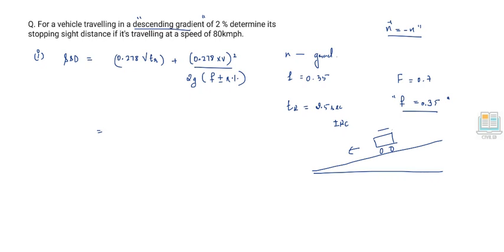The speed of the vehicle can increase here. That's why the n is negative. If it is negative, then the numerator is obviously a higher value. So the stopping sight distance required is higher, because there is higher velocity of the vehicle. To stop that moving vehicle, which is moving at a higher velocity, the distance required to stop it is always higher. Okay, because the gradient effect adds up here.